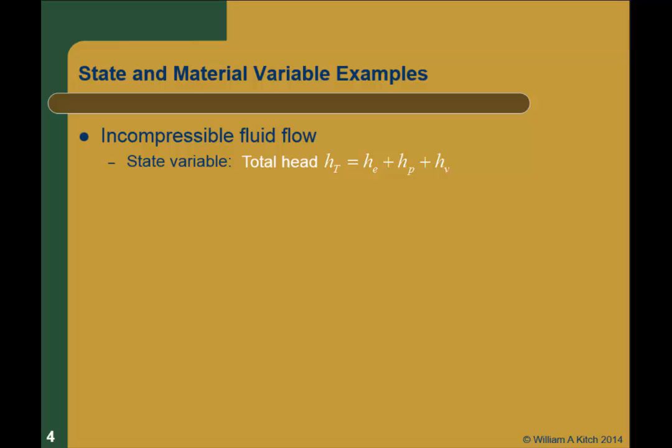It's not change in elevation head. It's not change in pressure head. It's not change in velocity. It's change in total head. That's what drives flow of water in pipes. That's what drives flow of water in soils. That's what drives flow of water in open channel flow. That is the state variable.